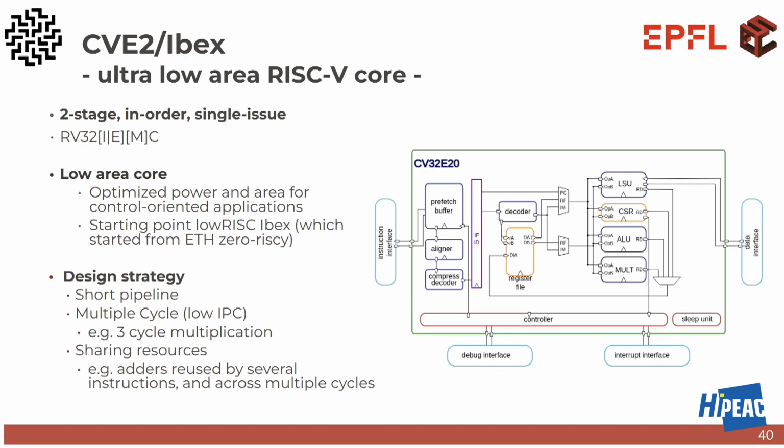Again, design choice. You don't have to do it like that. Then keep on going towards the right. There's a decoder. The decoder decodes the instructions. It checks whether it's an RVI instruction or E, understands what the registers are. Are you using register 1, 2, 3 or 5, 6, 7, whatever? It decides whether there is an addition, a multiplication, or whatever else, whatever we saw yesterday from the RISC-V ISA topic.